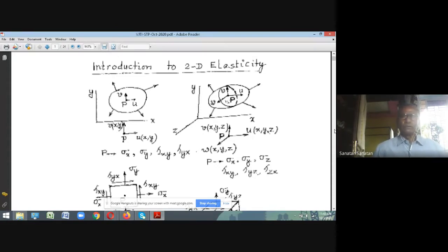All that you do is write the differential equations about the deformation process. Similarly, if you talk about fluid flow, then you also write differential equations: the Navier-Stokes equation, that is the momentum equation, then the continuity equation, then the energy equation. These are written in the form of differential equations.